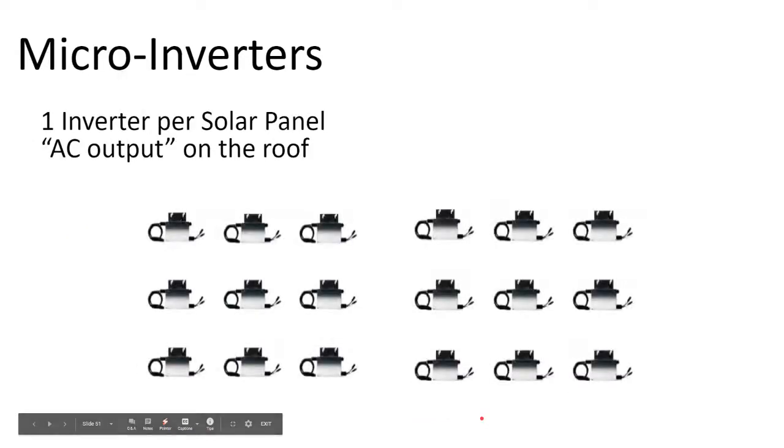The opposite approach is to use microinverters, where there's one inverter being installed behind every single module on the roof. Microinverters are particularly interesting because they produce AC output instead of DC output right up on the roof, eliminating the DC home run cable requirements, which require metal protecting the home run circuits. Which I think is nothing more than DC discrimination, because the metal is only there for physical protection, so there's no reason to differentiate between an AC source circuit and a DC source circuit, but that's a digression.